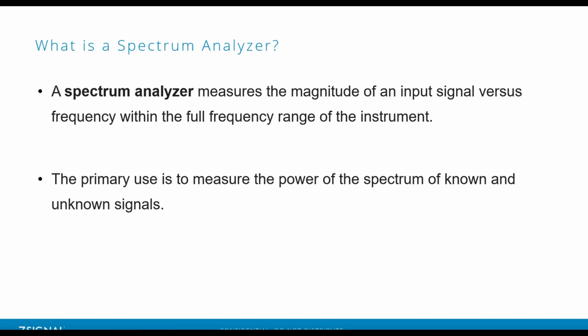And when it comes to these sources of interference, guys, there's really only 2 things that you can do. You use the spectrum analyzer to identify it, okay? And even if you don't know exactly what it is, there's only 2 things that you can do. You can either eliminate it, and if you can't eliminate it, then you use the system to identify where it's coming from so you can avoid it.